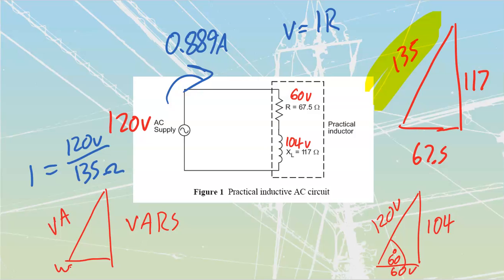We could take our current and multiply it by our voltage. If I take my current multiplied by my voltage, that's going to get me VA, right? That's literally volts times my amps over here. And then I could do the same through here, and the same through here, and that's going to get me my watts and my VARs. We might as well, because it's our common one.